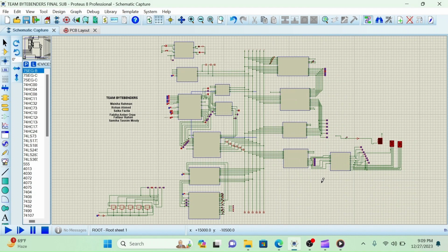This is a bus-centered computer where we have 12 main modules. The modules are connected to the bus directly or indirectly. The indirectly connected modules are actually connected through other modules to the bus. Here the modules are namely the clock, the program counter, the MAR or memory address register, the address selector, the input unit, the RAM, the instruction register, the controller sequencer, the accumulator, the arithmetic logic unit, the output unit, the B register. Here we will explain the operation of this whole system or our 6-bit computer and the modules one by one.